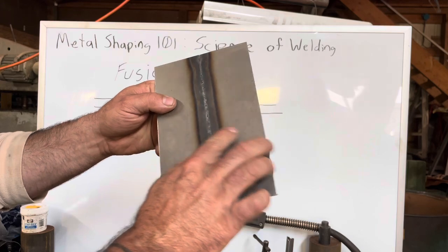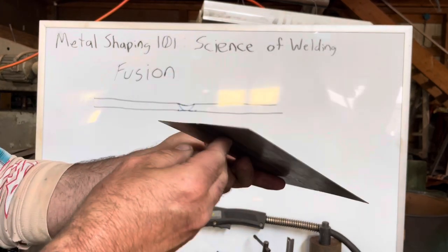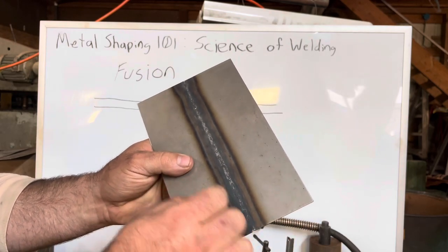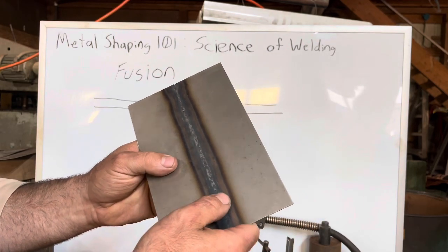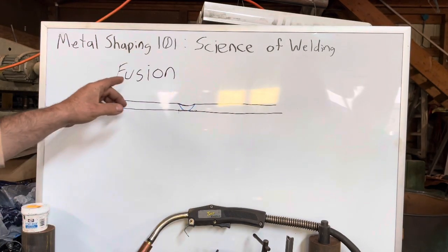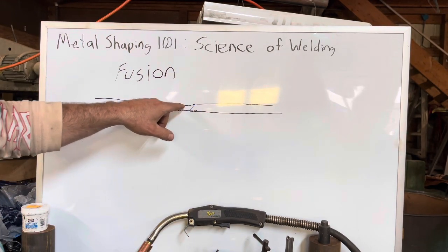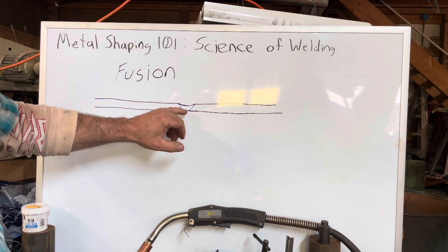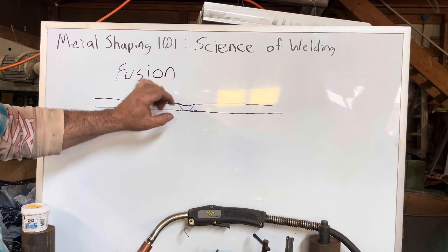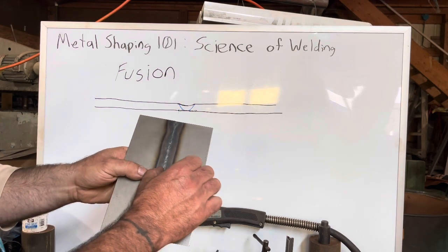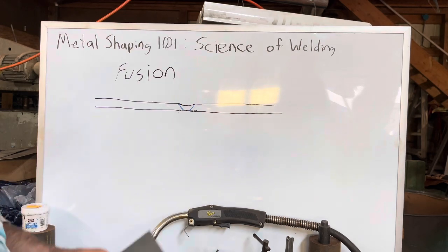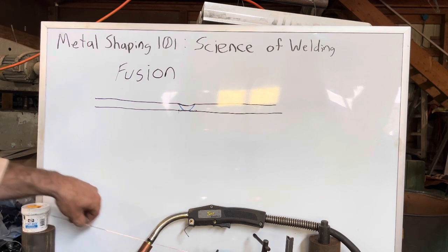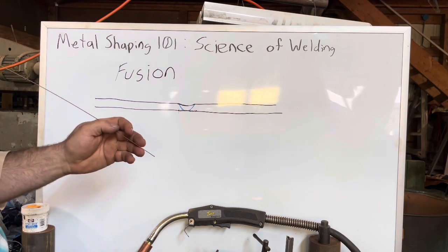This weld that I did here, it's very difficult to see. This was just a fusion. It was done with TIG, and there was no filler wire added to it whatsoever. What happens when we do that, the fusion is taking the two parent metals and mixing them and blending them and allowing them to join. But it's also scavenging from both edges a little bit of material. So it's actually slightly thinned out right there. And there's no reinforcement to the weld. So the next consideration that we need is to consider our filler.